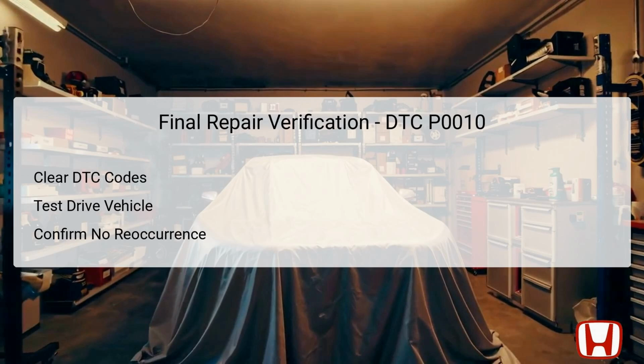To begin, the technician should clear any diagnostic trouble codes using the Honda diagnostic system. Once the DTCs are cleared, a test drive under varied driving conditions is essential to ensure that the repairs have rectified the underlying issues noted. Observing system responses and ensuring that the check engine light does not re-illuminate provides further confirmation of the repair's success.